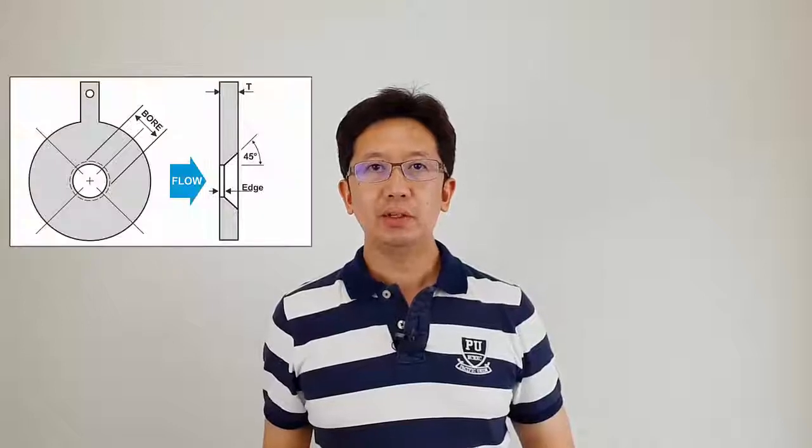For measurement selection, what is the flow meter? A flow meter is a device used to measure the volume or mass of a gas or liquid flow, which can be measured in a variety of ways such as differential pressure across an obstruction object, electromagnetic, interferential, ultrasonic, Coriolis force, etc. But the easiest one is the orifice plate.